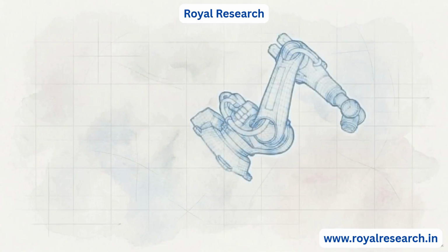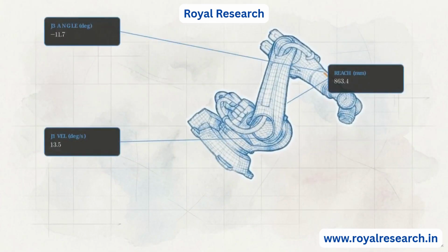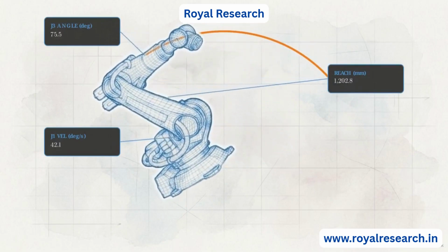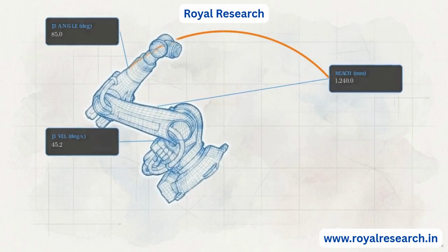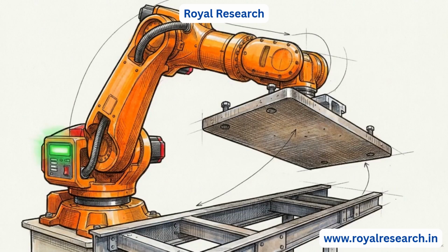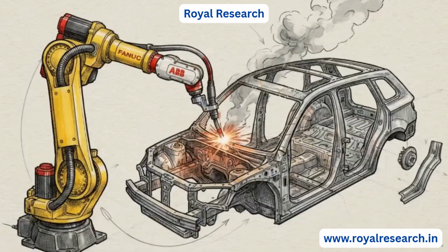Next, the offline programming engine calculates the required trajectories. It mathematically refines the robot's joints, verifies all physical constraints, and guarantees collision-free paths within that exact spatial geometry. Finally, a post-processor compiles this optimized logic and pushes the final code directly to the physical hardware on the floor, deploying the new task with zero interruption to the preceding workflow.